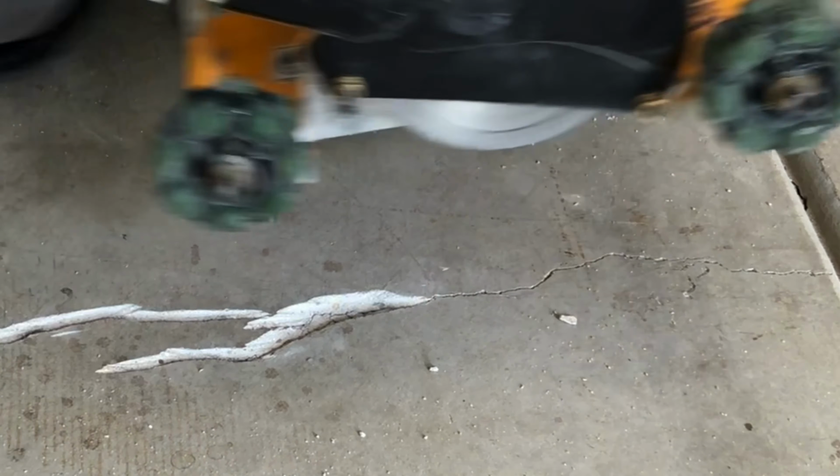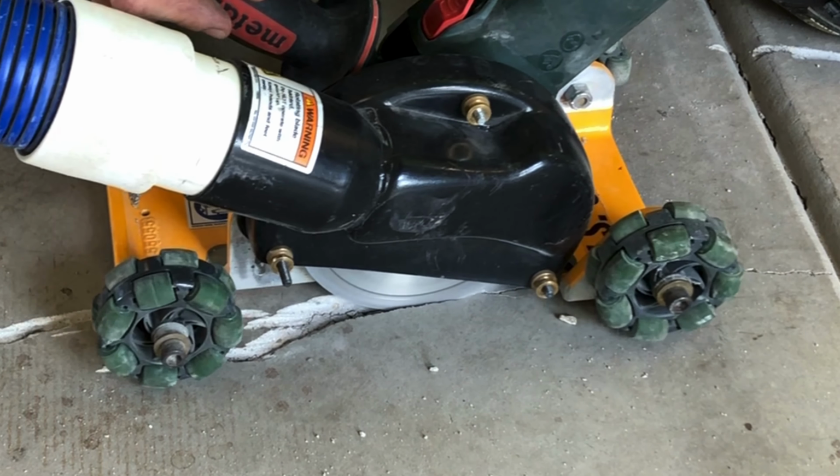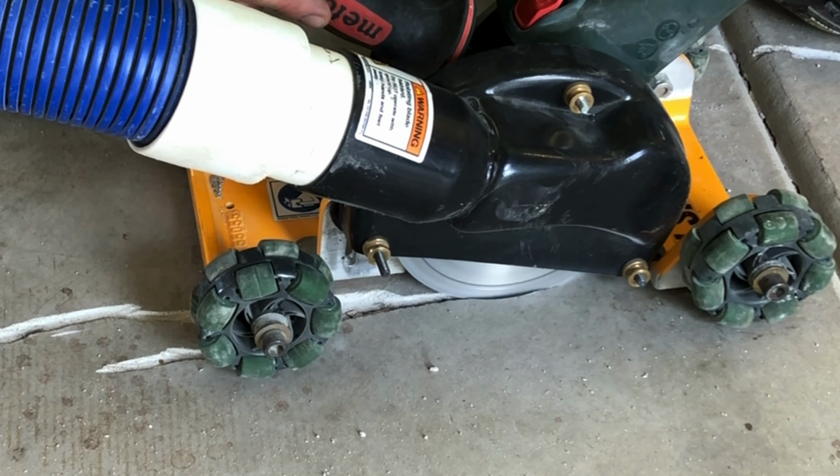So if we assume that the crack took place because there was movement in a rigid material, then it's safe to assume that the sidewalls of that crack or cracks are also going to be micro-cracked. From a surface preparation standpoint, the first thing that I'm going to try to fix is getting rid of anything that's structurally unsound. So if we assume that those sidewalls have micro cracks, that material has to go as well.